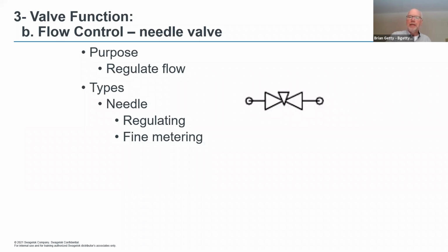Okay, needle valves. What do needle valves do? I have had technicians come to me and tell me, "Oh yeah, I use this needle valve to control my pressure." In the particular case he was talking about, it was a system with spray nozzles. All he was doing was regulating his flow, but on his gauges he would see a pressure. The reason he had a certain amount of pressure is because there was a certain amount of flow through these nozzles.